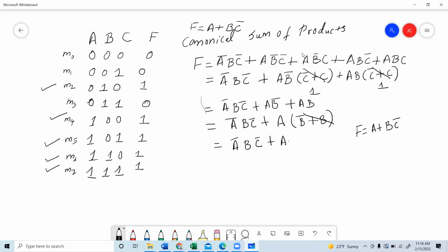Can someone solve this further, using some identity? I discussed this identity in the class. See, a lot of students think that this is the final circuit, we cannot reduce anymore, and just stop here. But you can. The final simplified Boolean expression is this one, which has 3 inputs of course, A, B, and C, but it has one 2-input AND gate and one 2-input OR gate. But here, if you see, this is a 3-input AND gate, right? Because we have 3 inputs to the AND gate. These are AND, right? AND form. And this is the OR form. So 3-input AND gate.